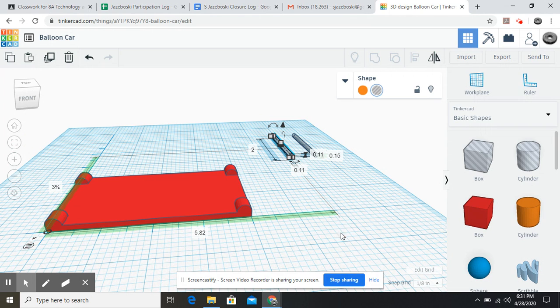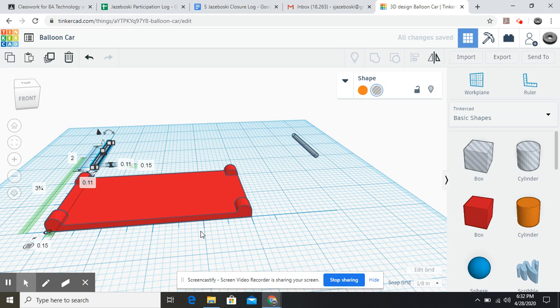After we get done with that, we'll now change our x and y. We can start with x, and we're going to change the x, once again, to 0.15. And then we're going to change the y to 1. The reason we're changing the y to 1 is that we're on midpoint, and our length of this is 2, so this is lining up an inch back. So what we want to do is move this down. The midpoint at 1 inch would be the middle of this. This is 2 inches, this is 2 inches. So we're going to type in 1.